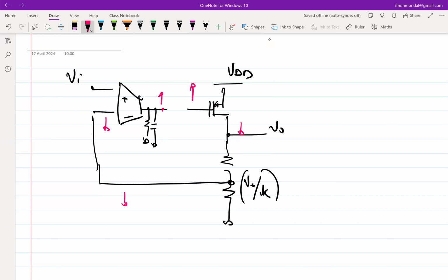It's in positive feedback. How did it suddenly become positive feedback? Because you are having another inversion here. There are two sets of inversions. One through the main GM, another through the second stage GM, because you have two common source stages now, equivalent to, right? You have two inversion stages put in negative feedback. So essentially, when you go around the loop, it becomes positive.